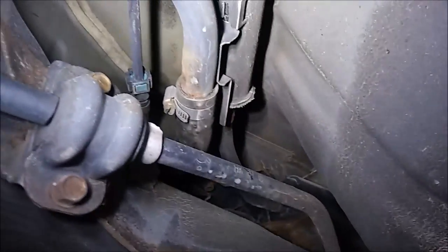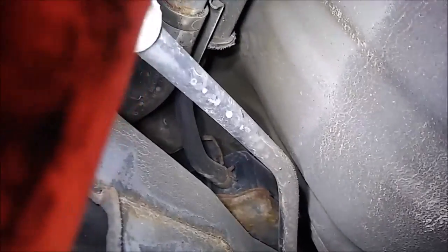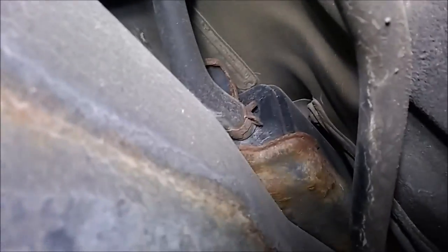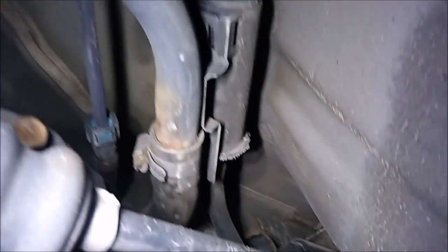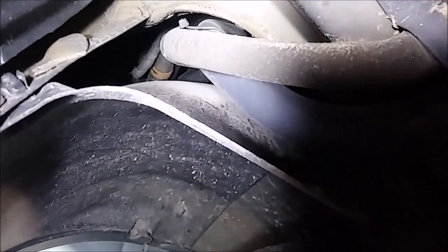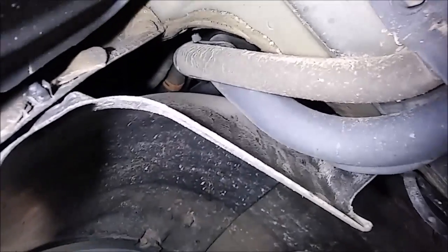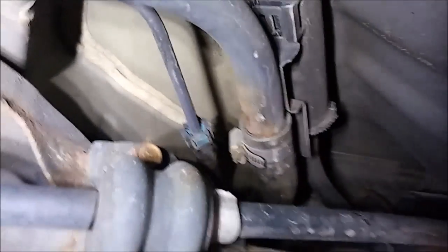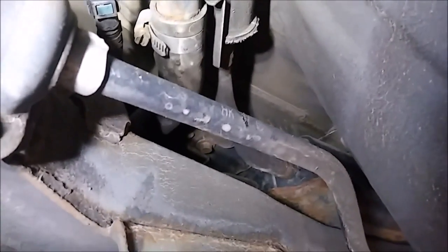If we follow this hose here, coming off of this canister, the one that I'm focused on right there, when we follow this up, we see an inline filter. And if we follow that up, it goes into the left rear wheel well area, and up there I can see the EVAP vent solenoid. It's kind of tough to see. But what we need to do to run this test manually is